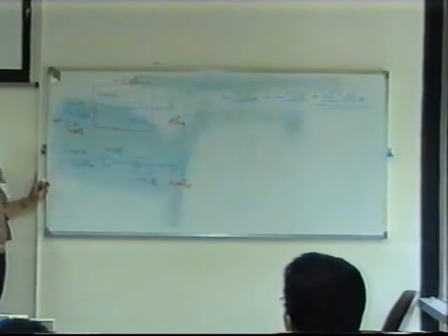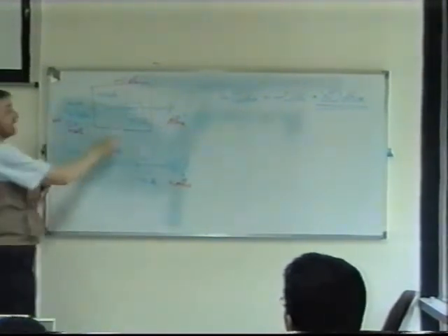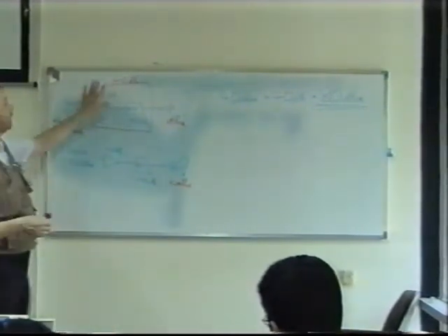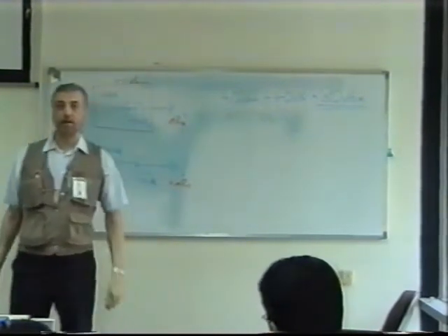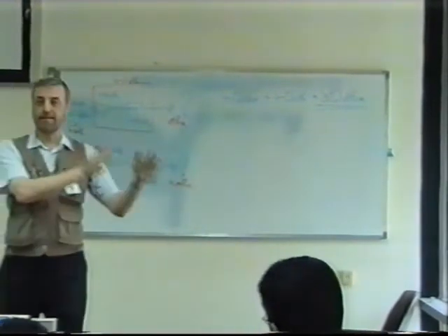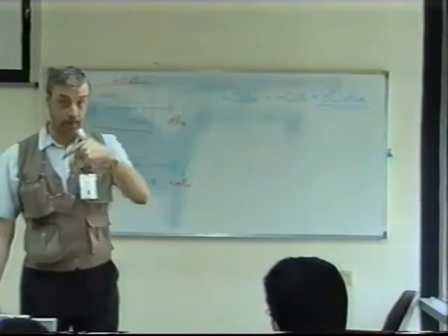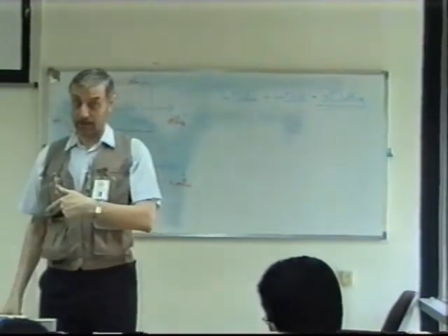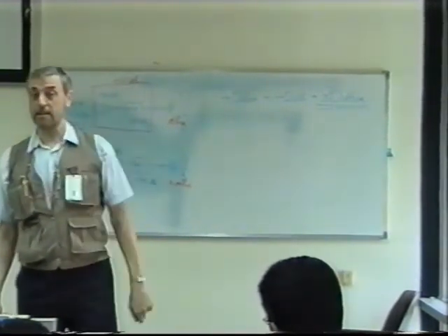Do you agree with that? A gain of 80 dBs on 1 milliwatt. So the output in dBm is 80 dBm. So that, not multiply, it is adding. That's right. Once you're dealing with dBm and you're dealing with dBs, you add and subtract. Which brings us to another advantage of using dBs, doesn't it? It is easier in that sense.